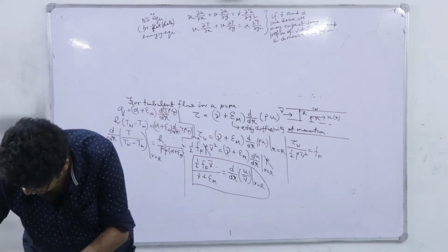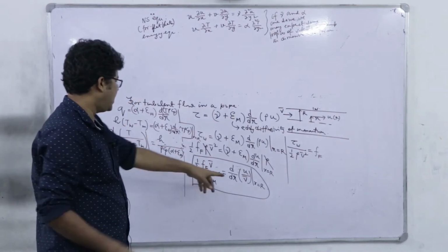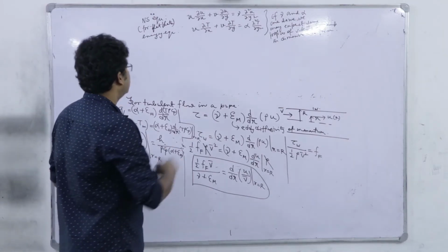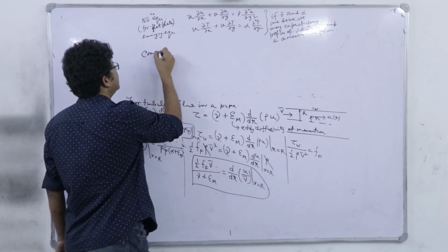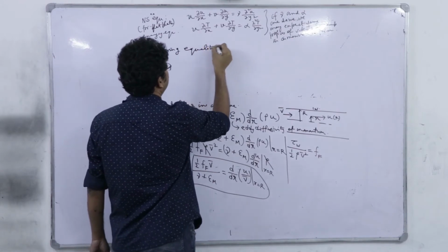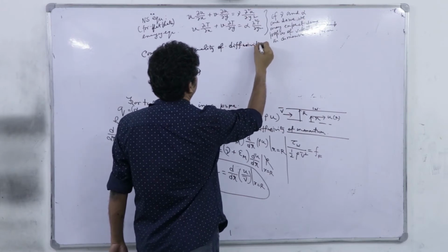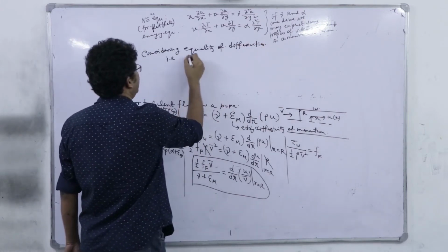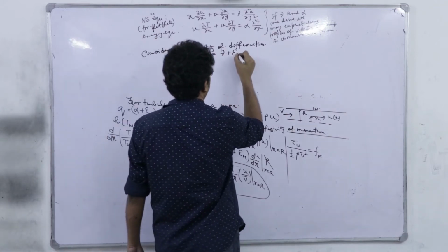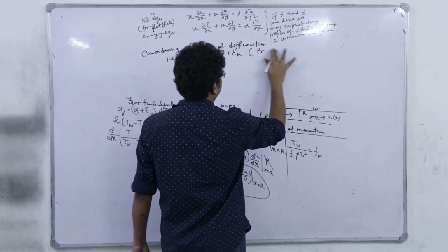So, what did he do? He simply equated these two dimensionless profiles, one is the velocity profile, another is the temperature profile for pipe flow at wall, right? And considering equality of diffusivities, that is, alpha plus epsilon h has been considered to be the same as nu plus epsilon m, right, which alternatively implies that Prandtl number is equal to 1.